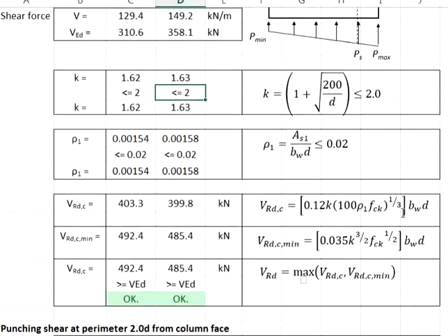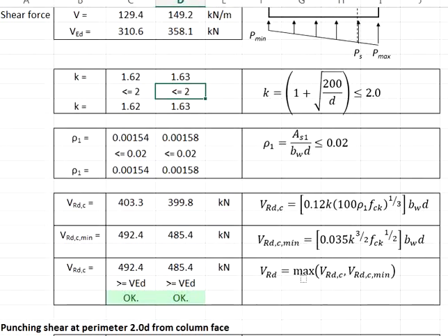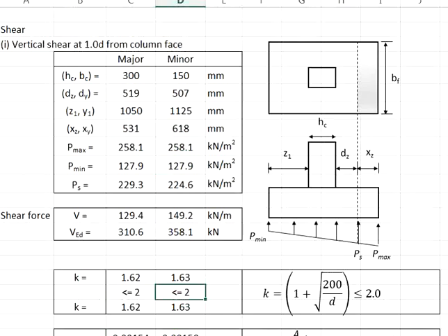And then in terms of the calculation of the shear resistance, it is also based on the effective depth. If you wish to make the arrangement of the reinforcement bar to the greatest advantage, you may swap the arrangement so that the minor axis becomes the main reinforcement and the major axis becomes the secondary reinforcement.